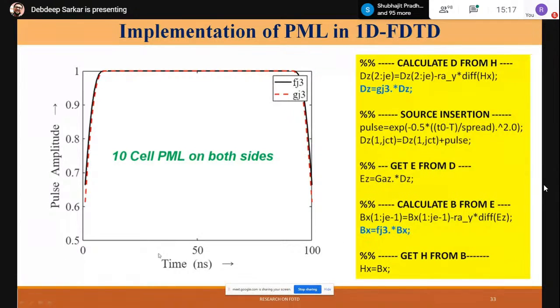In our case, I think this axis is probably wrong. This is the space axis. When I lifted this from MATLAB, it came as time by mistake, so please ignore that. These are actually the space locations. What is happening here is we want to put some absorbing layers at these regions. And how do we implement the absorbing layers numerically? That is the challenge. One idea that can readily come to the mind of people who know a little about absorbers is that we need to ensure that the wave is matched and then it is somehow getting absorbed.